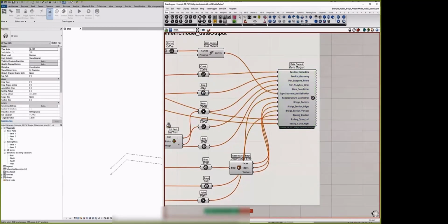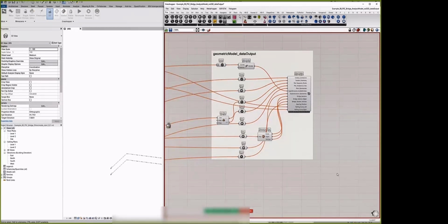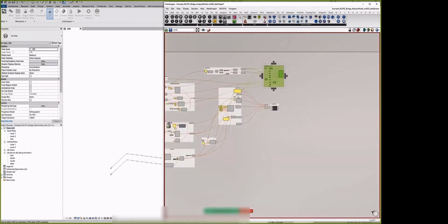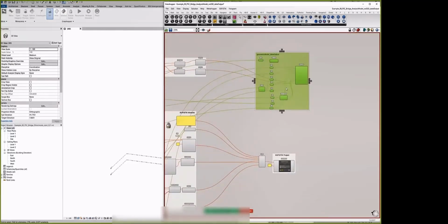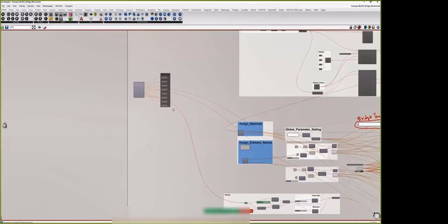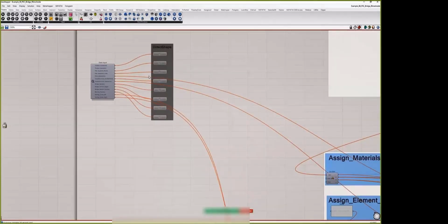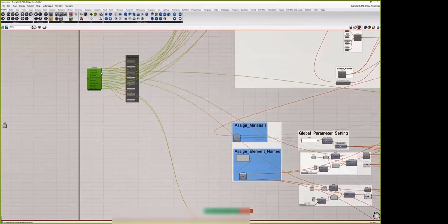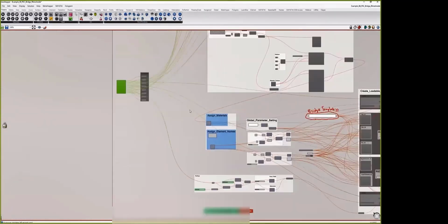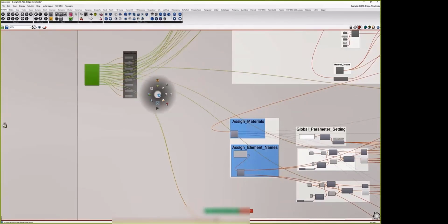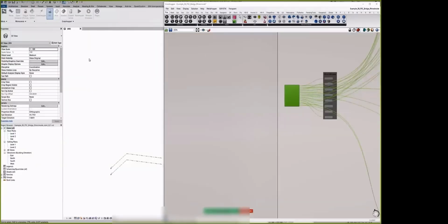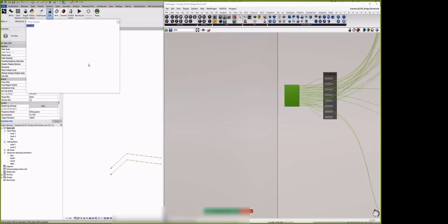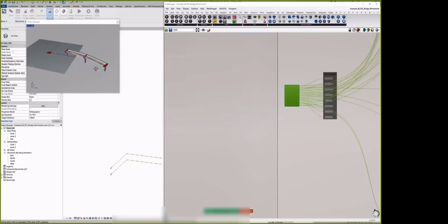And also the usability of results: sometimes you want to visualize structural analysis in Revit. Previously, it was never possible, but it's also possible now. I'm going to show that use case later. In this case, it's a bridge construction, again generated from the Sofistik Grasshopper plugin, which allows very flexible bridge design, and we can also calculate all these bridge analytical components or elements directly from Sofistik.